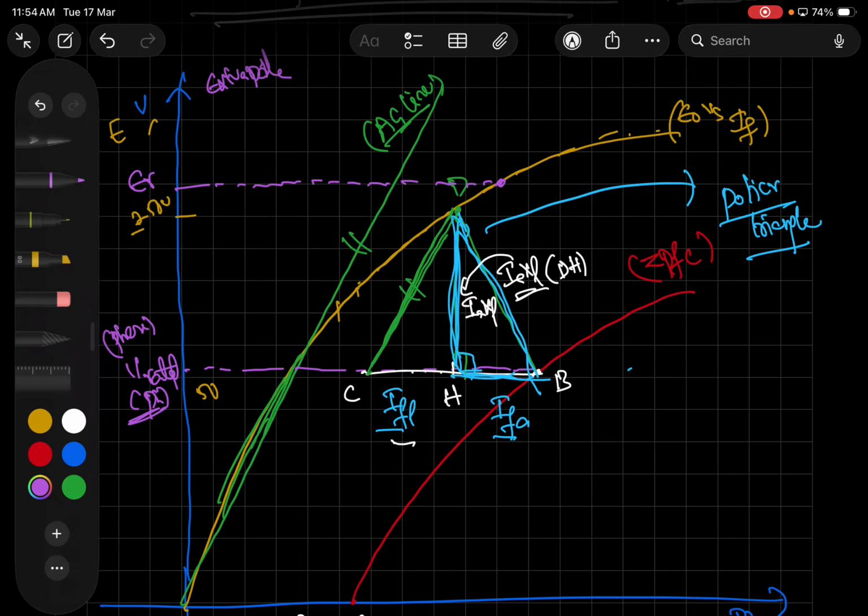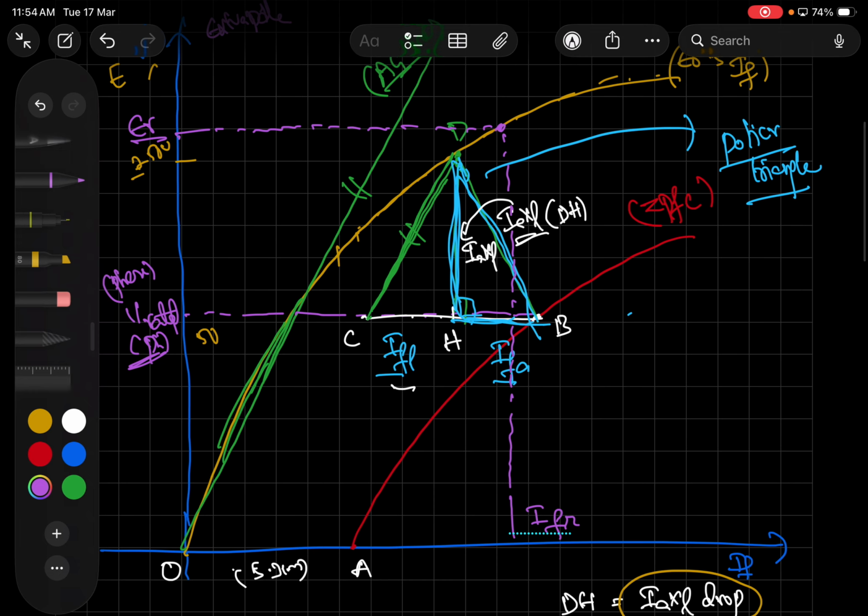From there, again you have to draw a dotted line onto the x-axis, onto the field current here. From ER, whatever the ER that you got from the formula, locate that point ER, draw the extended dotted line onto the OCC from that point here. Then draw a dotted line onto the axis. This field current I am considering as IFR.